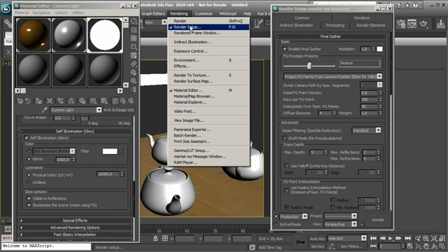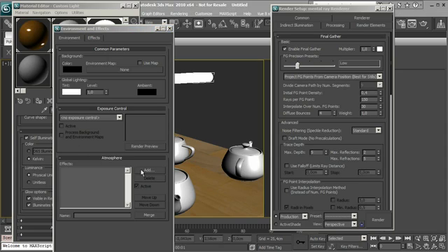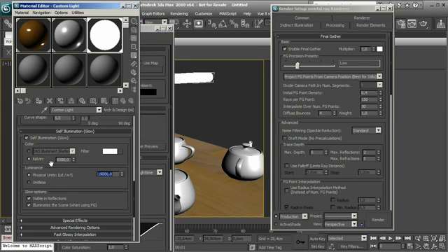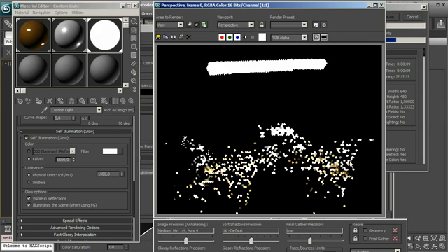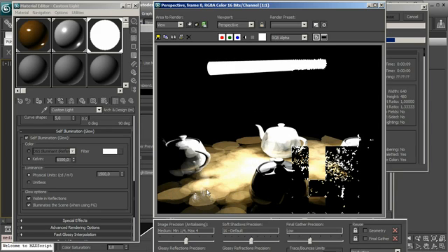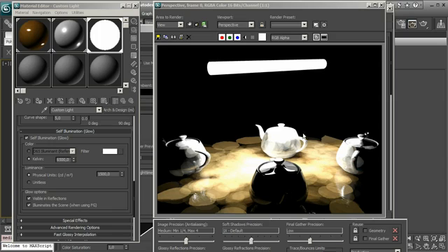let's go also to the exposure control, and let's add a mental ray photographic exposure control, and let's set to indoor nighttime, and we have 200 film speed ISO, and we can go back to the illumination to use a more real illumination value. So let's go back to 1000.5. Let's make a render test. Okay, and you see that actually it's really blocky illumination, so we can go back to a less luminance. So let's try with 500.